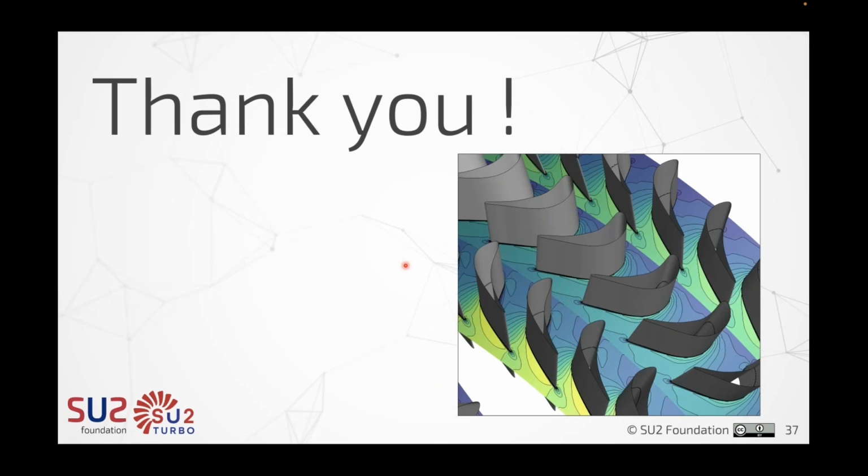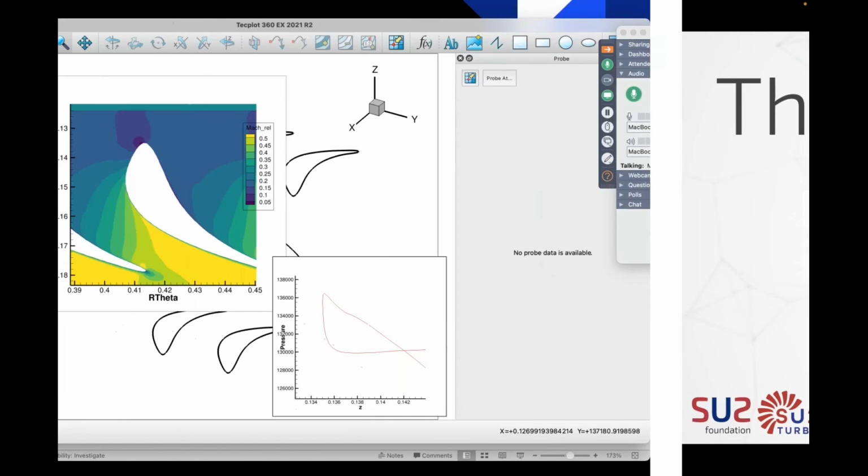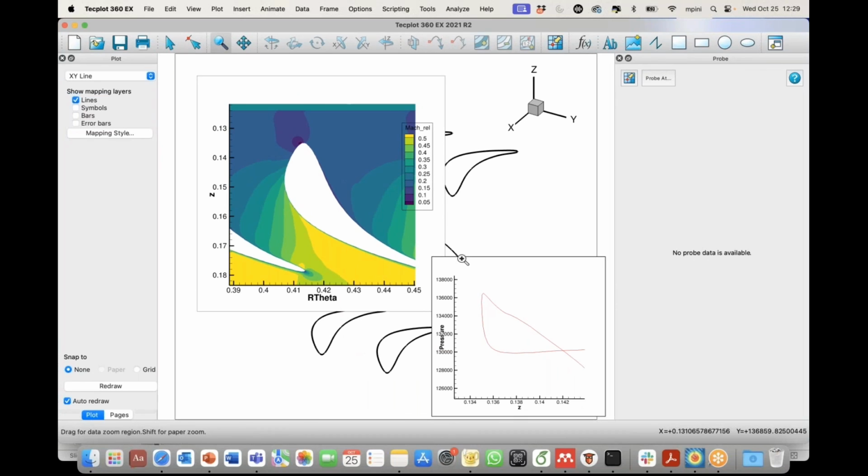I guess, what do you need to do to fix that? Well, there are multiple things that you can do. Not talking specifically about this case, what you see here basically means that there's a sort of mismatch between the flow field that the rotor is delivering and what the following stator is designed for.